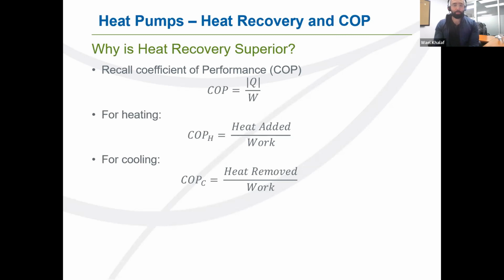Since heat pumps just use the refrigeration cycle to move heat from one area to another, I can basically remove the heat from the gyms, the offices, the common spaces, and take that heat and dump it to heat the pool water. And that's a form of energy recovery where I can take credit for both the cooling aspect of my heat pump and the heating aspect.